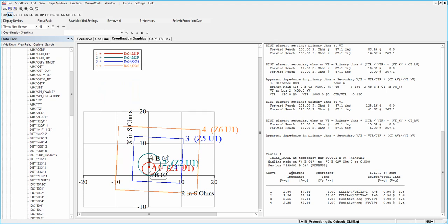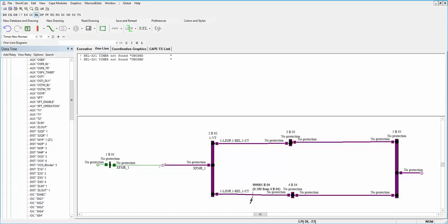Right now the right side window says that the 3-phase fault is applied on the line, mid of the line between bus 4 and 2, and the summary of the relay settings pops up here. It shows that after one cycle zone 1 will detect it, but zone 2 will work after 11 seconds. So we can define the trip logic for this relay too.